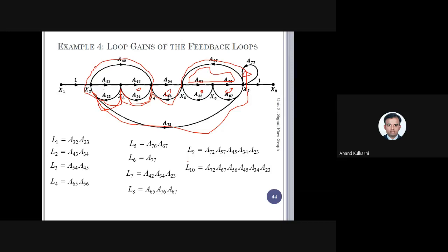No. Here we have not done the other part yet. First and foremost, in a given signal flow graph, we first find the forward paths. We have already found 3 forward paths. Then we have to find how many single loops are available. There are 10 single loops in total. Then we will go to the option where we take 2 non-touching loops, taken 2 at a time. Are you getting it?